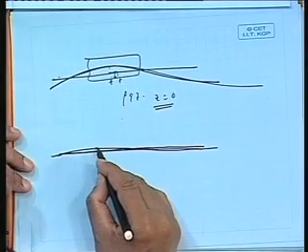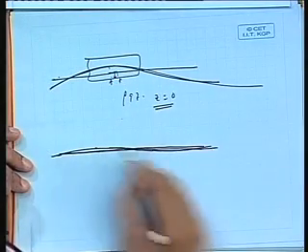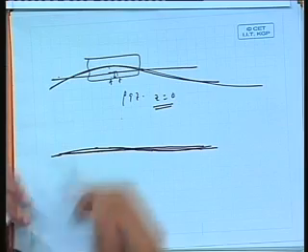So the dynamic pressure keeps varying along the wave. Yeah, of course it will vary. Obviously, it will vary. Now I just showed the crest because it is the most critical. But at every point, it is exactly of that magnitude where the dynamic pressure and the static pressure, when added together, make a positive pressure, and on the surface make it exactly 0. On this surface it will be exactly 0, balancing it, because it has to be 0. In fact, that is the condition based on which this is found out, that it should be 0 on the surface. Obviously, on the surface it should be 0, basically atmospheric pressure, which is taken as a datum line. So this is an important point we have to always remember.